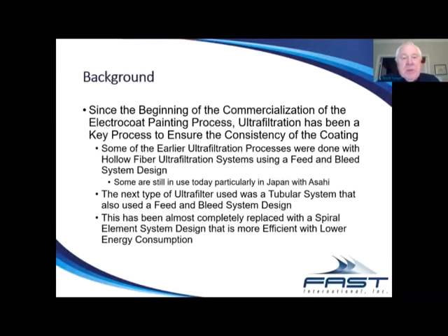Okay, since the commercialization of E-coat, ultrafiltration has been a key process and is really there to ensure the consistency of the coating. Some of the earlier filtration processes were done using hollow fibers. Some of you may be around long enough to remember that. There's still some being used, mostly in Japan. And then the next systems were tubular systems. Both of those were feed and bleed systems. And they have been almost completely replaced now by spiral element because they are more efficient with lower energy consumption.